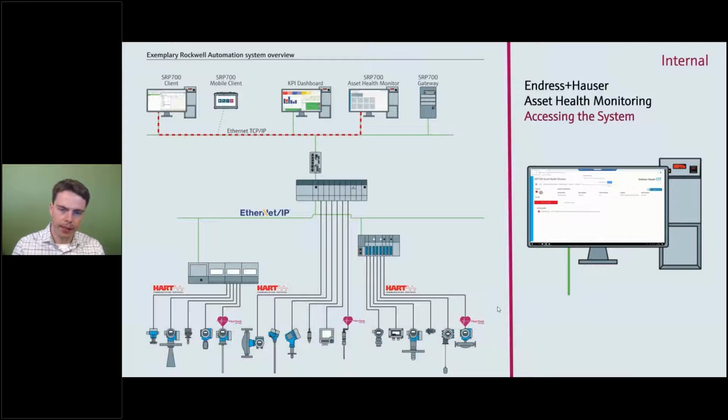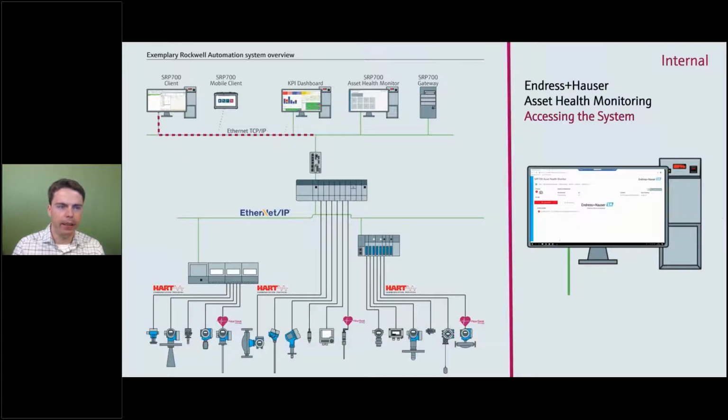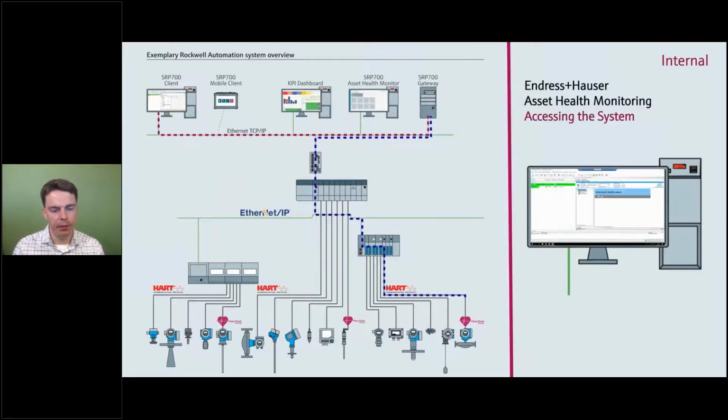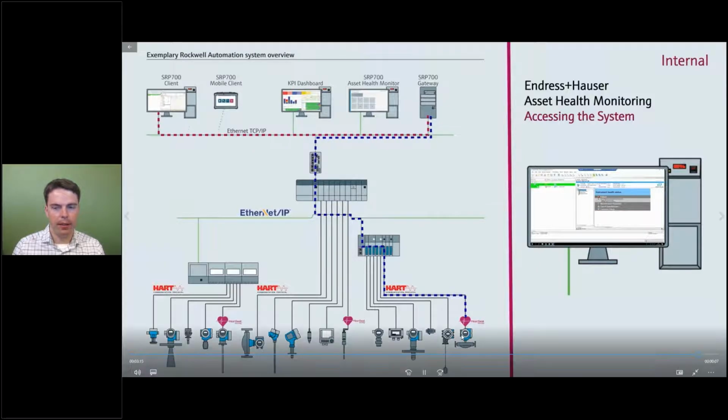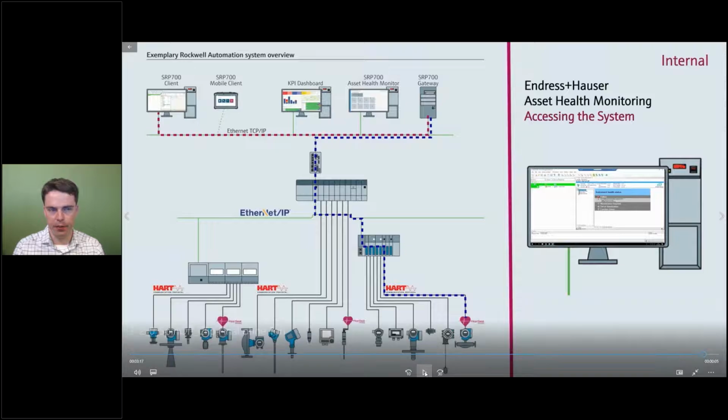The web server will actually trigger in the back that FieldCare will open, and FieldCare will then automatically connect to the gateway because it knows from that web page where to find it, and the gateway will patch you through to the device. And now you can do heartbeat verification, and you can do a configuration or troubleshooting of the device.